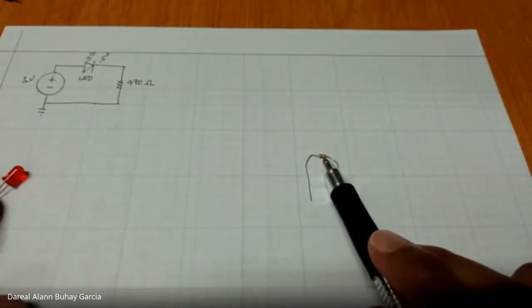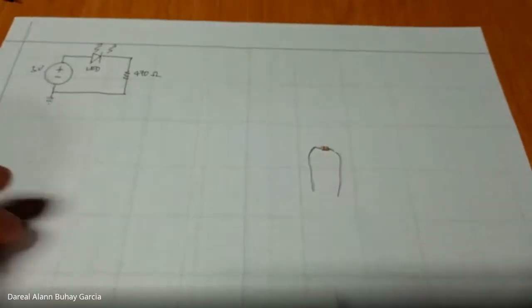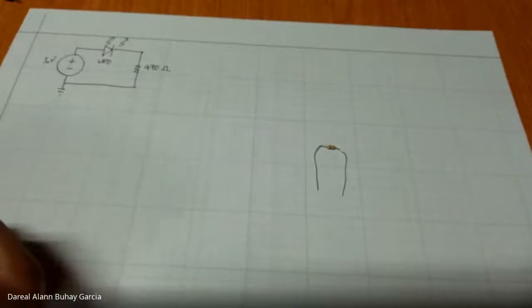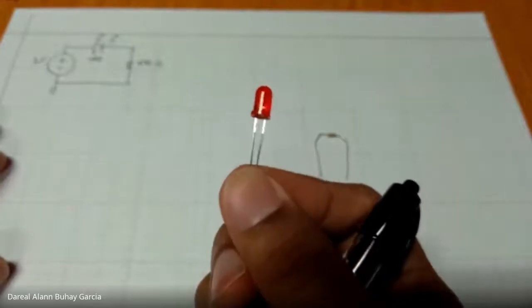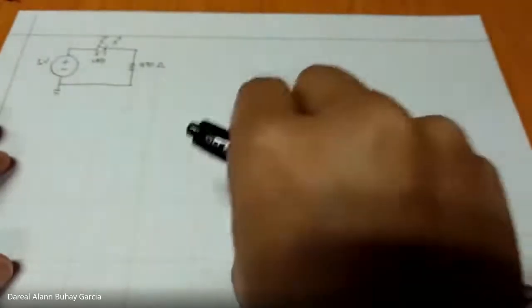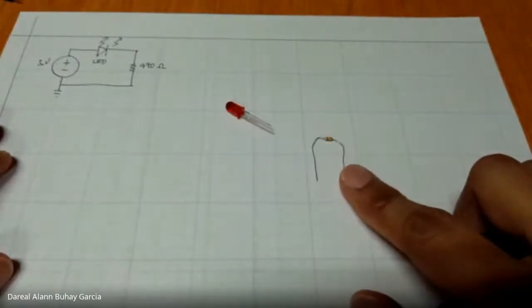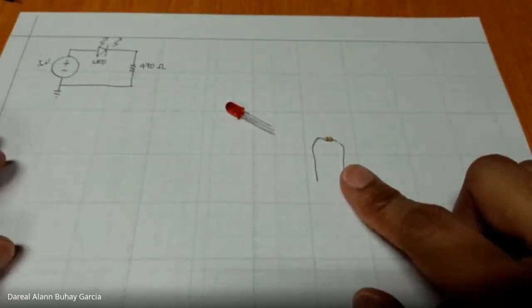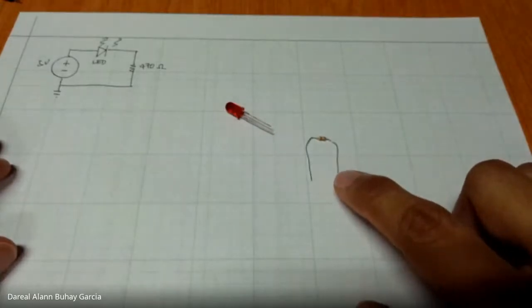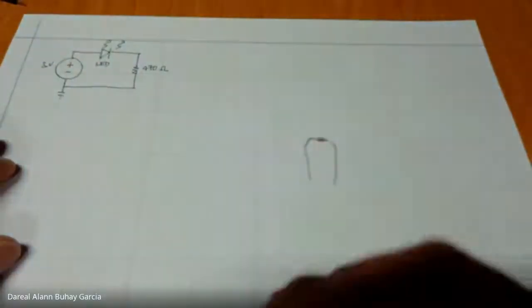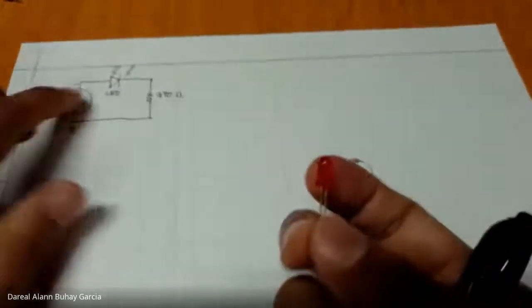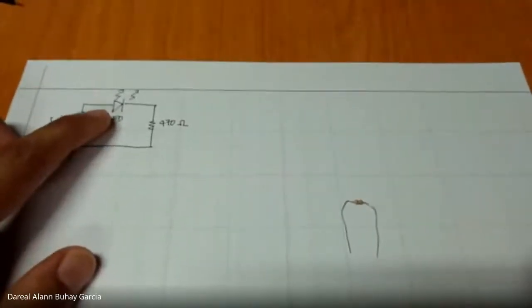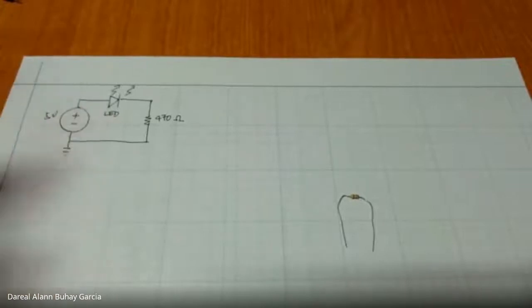Anyway, if we don't have a multimeter. The critical part is our LED. The resistor is okay because it is a non-polarized device. So it has no positive or negative, no anode or cathode. Unlike the diode, which has positive and negative and cannot be reversed. We know that in the operation of a diode, it conducts current in only one direction. So if it is reversed, it won't work. It won't light up.